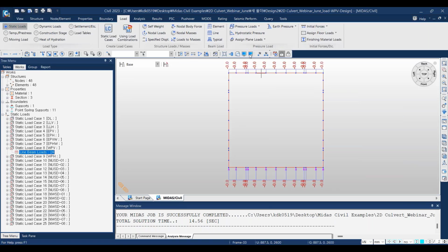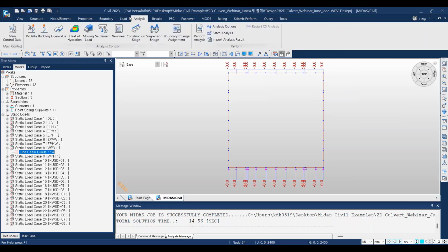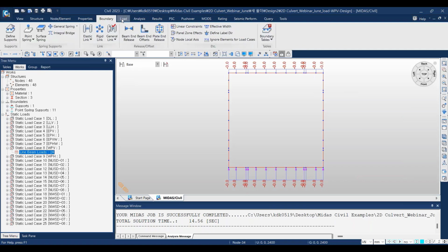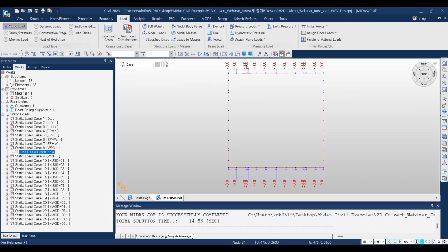For this case here, we had load applied here for 13, 15 and 45. But when you make the design load here, you need to make sure that you don't have a minus sign, a negative value, when you make the addition of the top and the bottom load for the buoyancy, as explained in the PPT file.